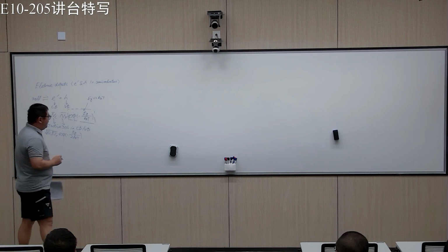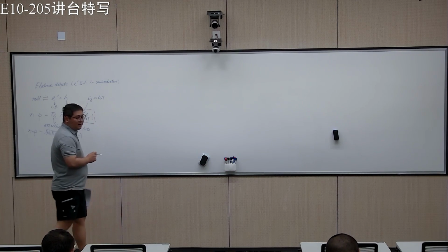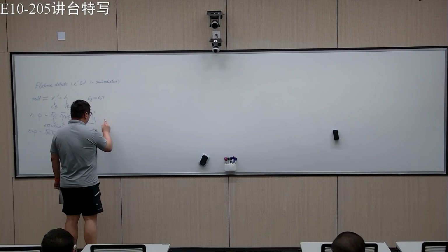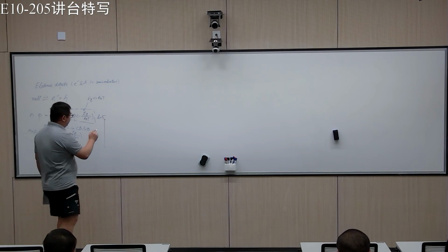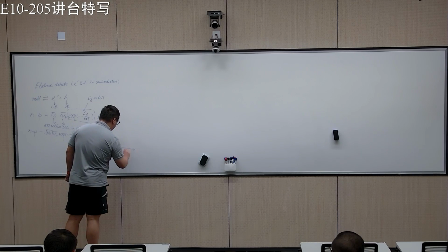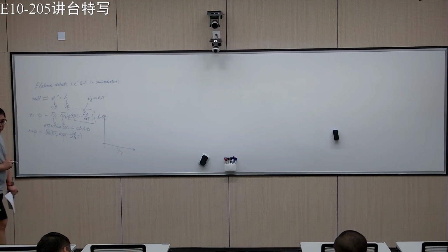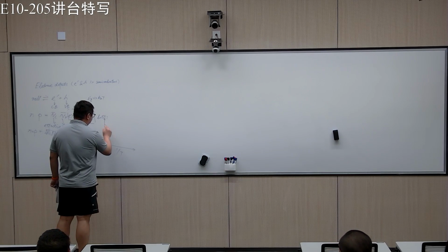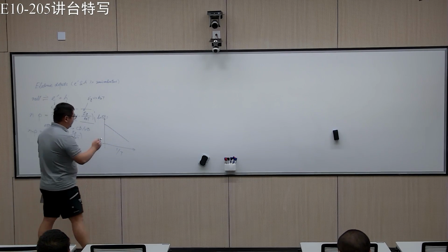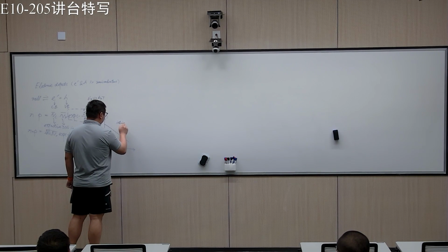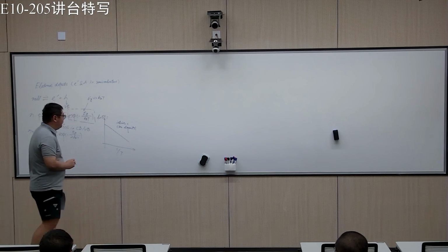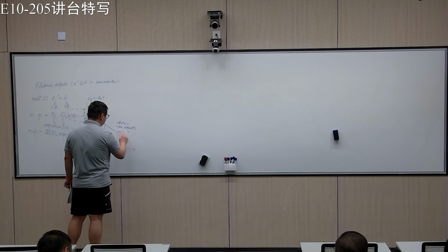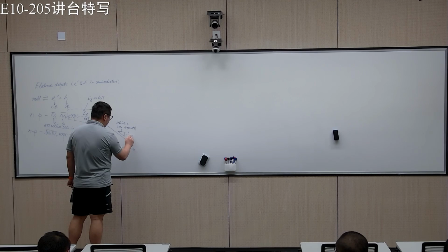Therefore, if you plot the logarithm of sigma, where sigma means conductivity, for something like silicon, versus 1 over T, what you usually find is that in this intrinsic region, which means no dopants, you have some activated behavior. Again, the slope should be Eg over 2kB.